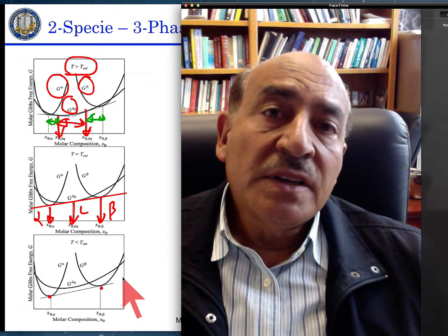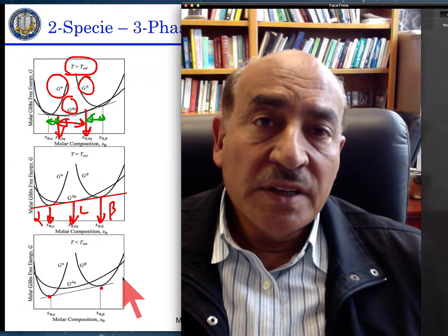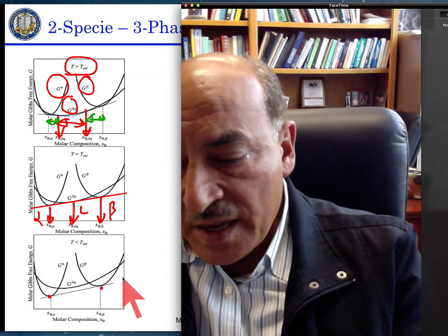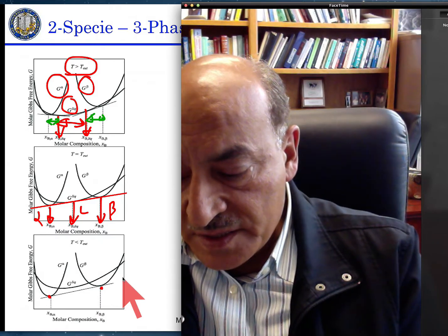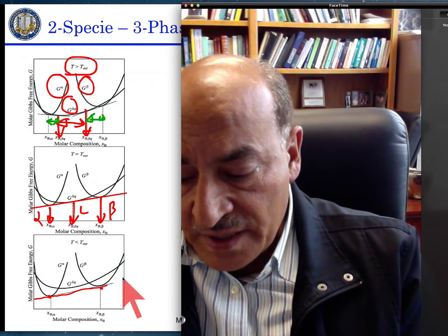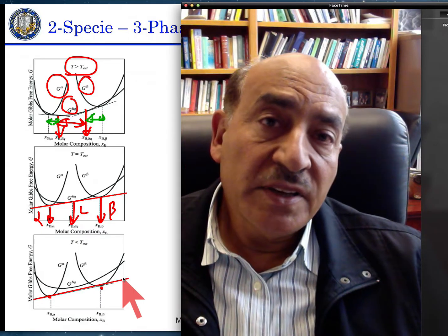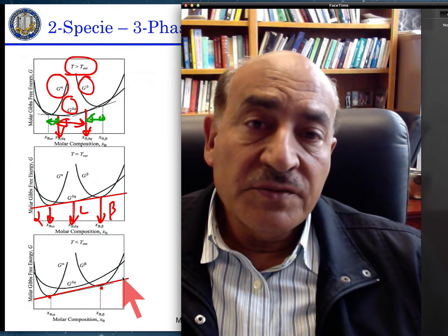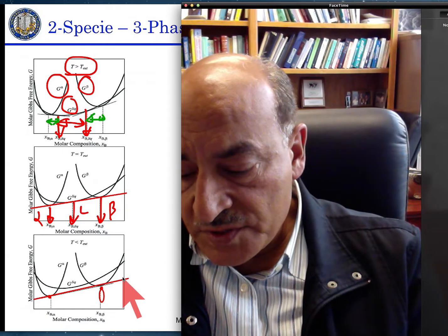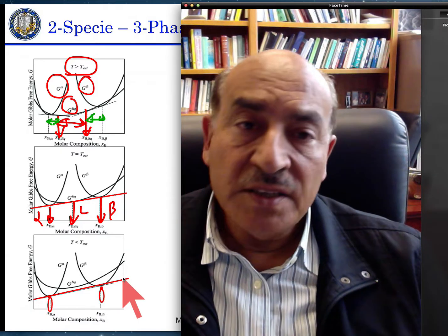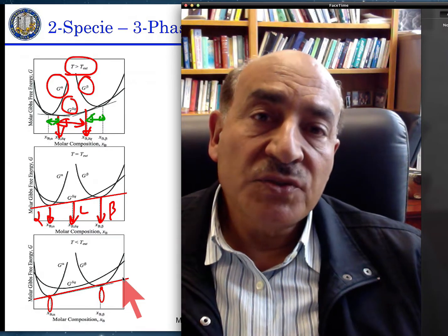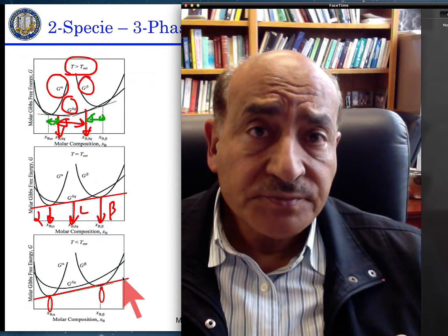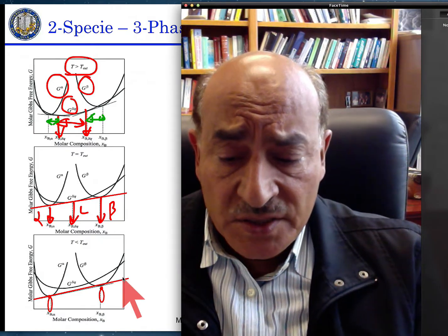The stable phases are going to be the liquid, the solid alpha phase, and the solid beta phase, and the stability condition is expressed by the two solids being lower than the liquid. Then the equilibrium condition is expressed by the common tangent of the two, giving you these two solutions. So I have a solution here and a solution here for the two concentrations corresponding to the two phases.